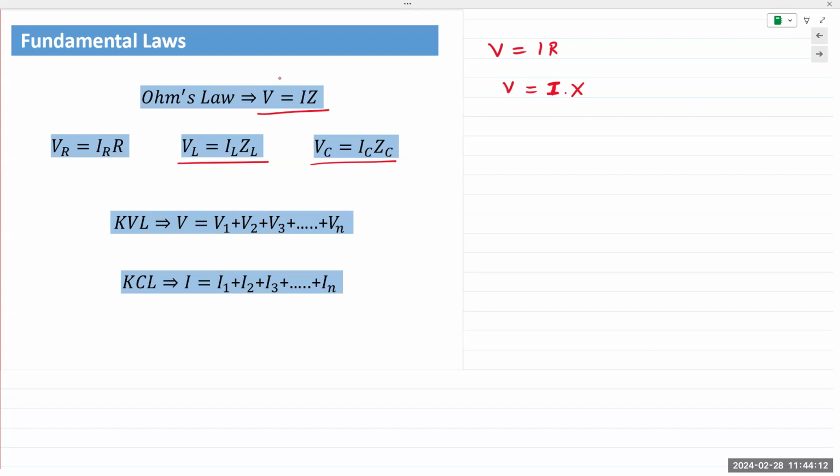So if you wish to go a little bit further, you can take the results of lab 6. You would have magnitude and phase for the inductor voltage, the capacitor voltage, the resistor voltage, and the source. Apply KVL, meaning just sum up all of those values, and you should get 0.